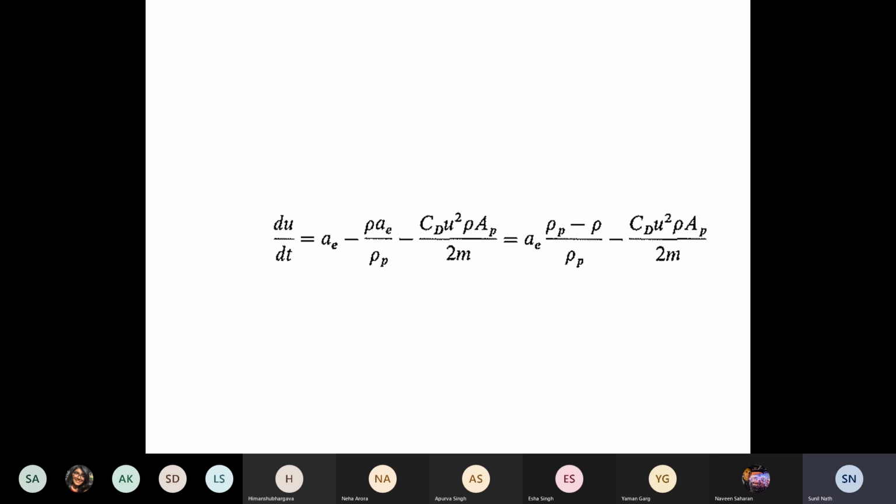So my question is, now knock off that acceleration du/dt term and obtain it, because slowly that acceleration term is going to decrease because of the way the drag force keeps increasing as the u keeps increasing. And if it becomes very small, I can neglect it. And then I have a regime where the velocity u approaches a maximal and constant value. I want you to find that maximal or terminal condition value and give it a subscript T or M, for terminal or maximal.